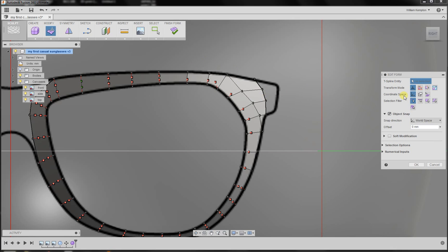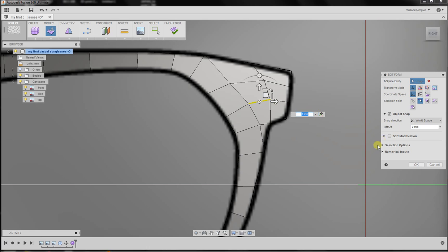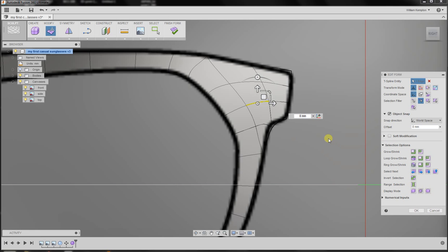And then I'll go in, I'll press edge, and I'll make a nice last group of faces by holding down the L button, and I can rotate them, and I can even scale them down so that the line becomes sharper, and also scaling it down from here. That is a nice finish. We can now view it as a smooth display, and we can see that we have some lines here that